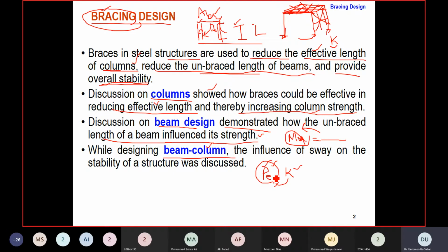So strengths are also involved in the beam column strengths. Similarly, when you apply the checks, you calculate the moment capacities to use the interaction equations for the beam column design. There you need the strength factors also, meaning moment capacities, and those depend on the effective length factors and similarly on the bracing design of your steel frame.